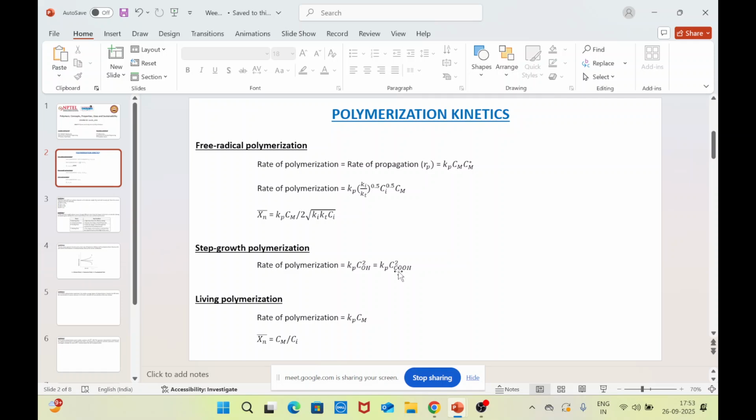In case of the extrusion process, the polymer that you are trying to process is going to be present in the form of polymer pellets, or in case of polymer solids, chunks. These polymer pellets or chunks are going to be fed into the screw extruder using a hopper.